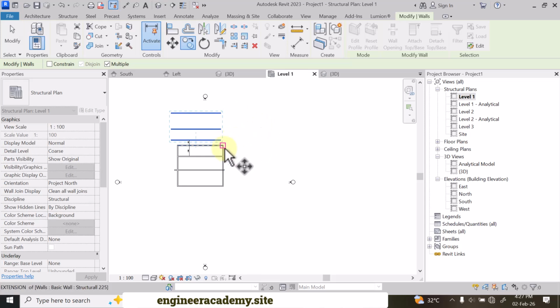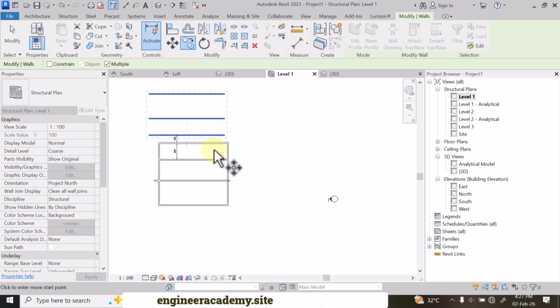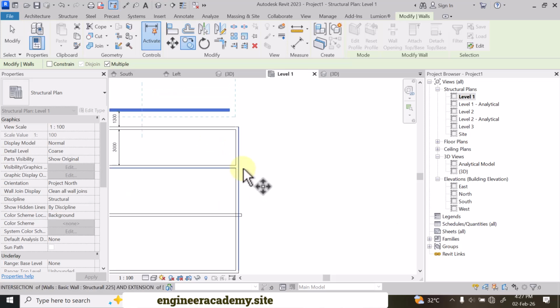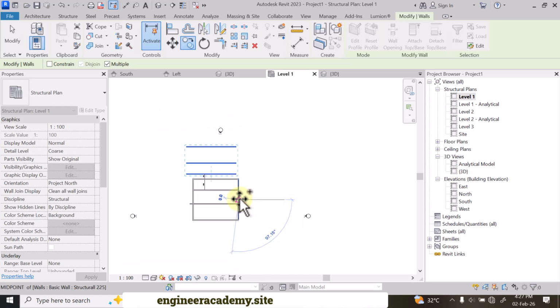So if I click now, it means I'm going to be picking it from that particular reference point. Let's assume I want to pick it from this wall. Then this wall now becomes my reference point. So I click. Once I click, it is ready to move. And as I'm moving it, you see that I am actually moving a copy of it.